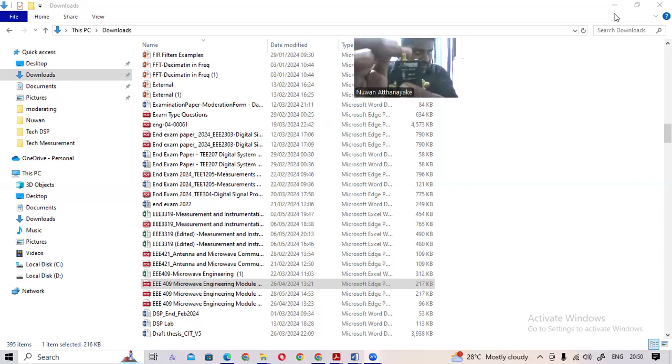And from here, the inductor is there. So the inductor will block the AC signal, and you will get the DC signal here. So if you give a DC plus AC signal, from this side you can get the pure AC one, and this side you can get the pure DC signal. Okay, so this is a bias T. That is also true.